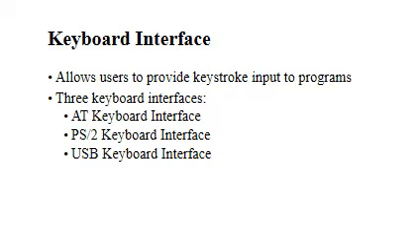PS2 keyboards use the 6-pin mini DIN connector. On the other side, the PS2 keyboards use the same Intel 8042 equivalent interface chip as the AT keyboard, which is also assigned IRQ1 and input-output base address 0060.